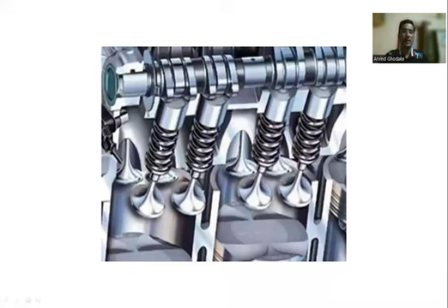Then this is also a diagrammatic representation of the valve mechanism. So here a spring is provided, then it will be attached with the camshaft, and cam is there. So once cam gets rotated, the inlet and outlet valve get actuated depending on the type of the stroke. During the inlet stroke, the inlet valve will open and the air-fuel charge will come inside the cylinder.